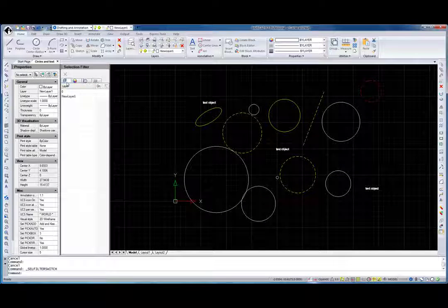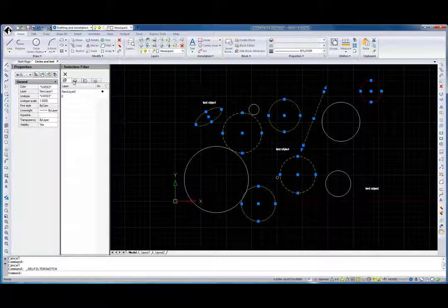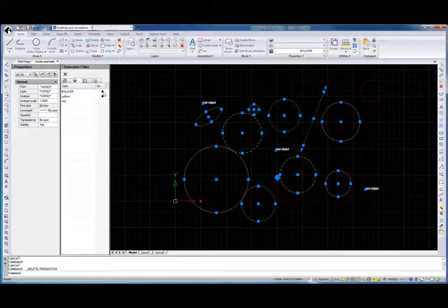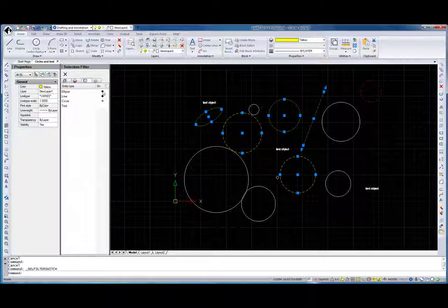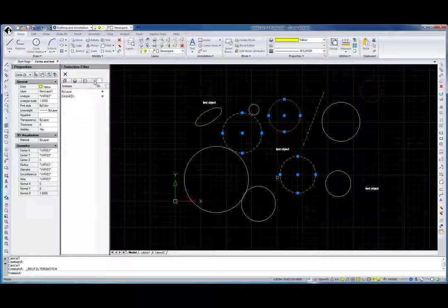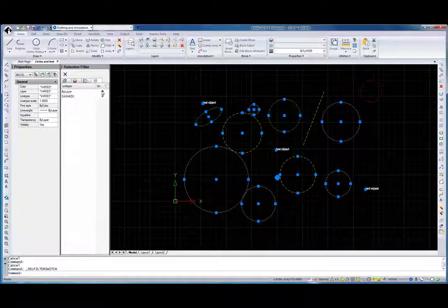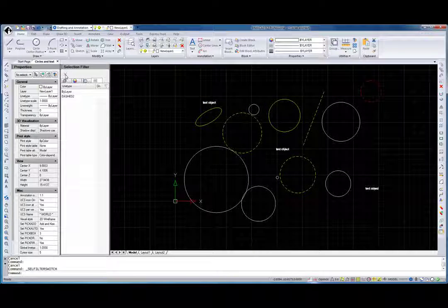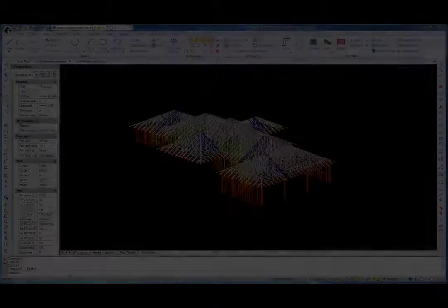For example, if I want to select all yellow circles on layer 1 with the dashed line type, I turn all of these filters on and see that all entities with specified properties are highlighted. You can use the clear button that turns off all filters on all tabs.